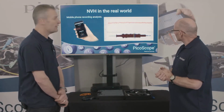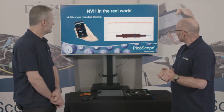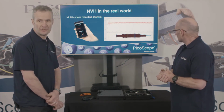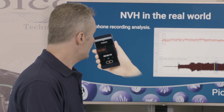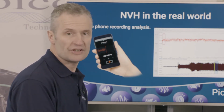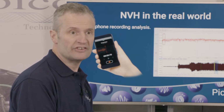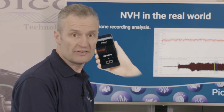Now, is that an offending frequency? It's unlikely, but the key information here is we've been able to capture the audio. We know the engine speed, we know the level of E2, and from that we can make an informed decision as to whether or not this is a component rotating at engine speed, whether it's relative to engine speed or not.